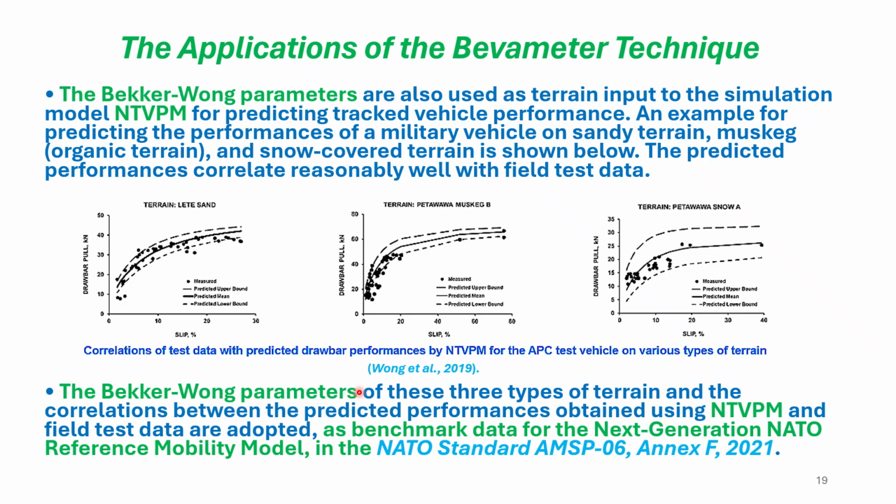The Bekker-Wong parameters of these three types of terrain and the correlations between the predicted performances obtained using NTVPM and field test data are adopted as benchmark data for the next generation NATO reference mobility model in the NATO standard AMSP-06 Annex F published in 2021.